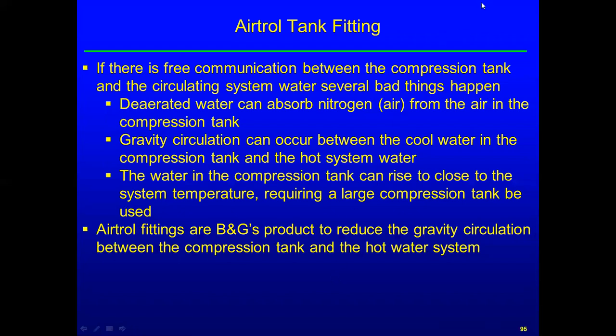Airtrol tank fitting. If there is free communication between the compression tank and the circulating system water, several bad things happen. I think we've already talked about this. Deaerated water can absorb nitrogen from the air in the compression tank, and we can get gravity circulation between the cold water in the compression tank and the hot system water. This is for a heating system primarily.